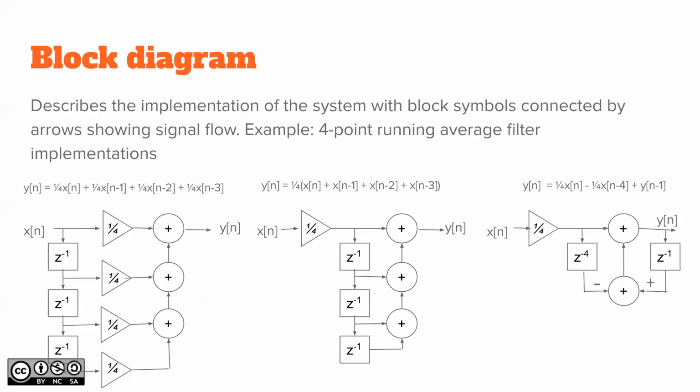But in addition to that, there is the logic part, how you multiply binary numbers together. In addition, you just add the bits with carry flag. But in multiplication, you actually are doing each bit multiplication and adding those. That's the quick and dirty, cheap-on-silicon version of doing multiplication. So practically, the integer multiplication is done in a loop.